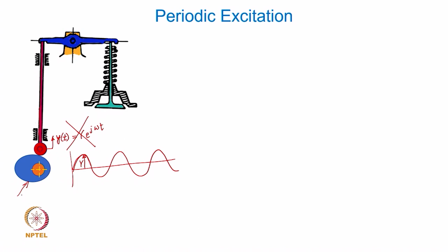We have learnt about the cycloidal cam profile, which has the best dynamic characteristics, and therefore the excitation function that it will generate is not going to be harmonic, right? So, when it is not harmonic, how do we cater to that kind of situation? How do we find the response of the system to such an excitation is what we are going to discuss today.